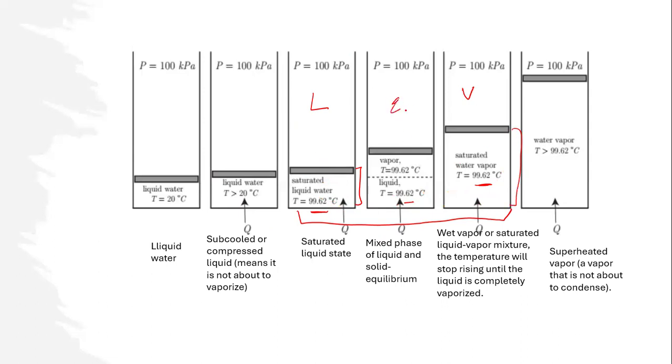And then here we have what you call the equilibrium. Let me re-explain this, because this is the graph that I said I will explain during this session. When the temperature reaches the boiling point of our pure substance, in this case water, we're going to have saturated liquid. The moment we include the word saturated, that means it is liquid mixed with water vapor. But you have to understand that at the beginning our quality is a little bit less. I'll explain the quality part in this lesson.